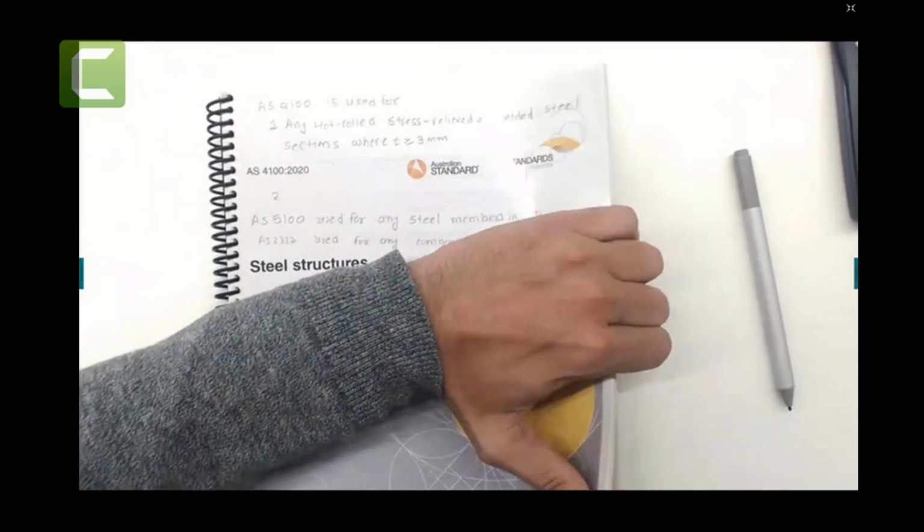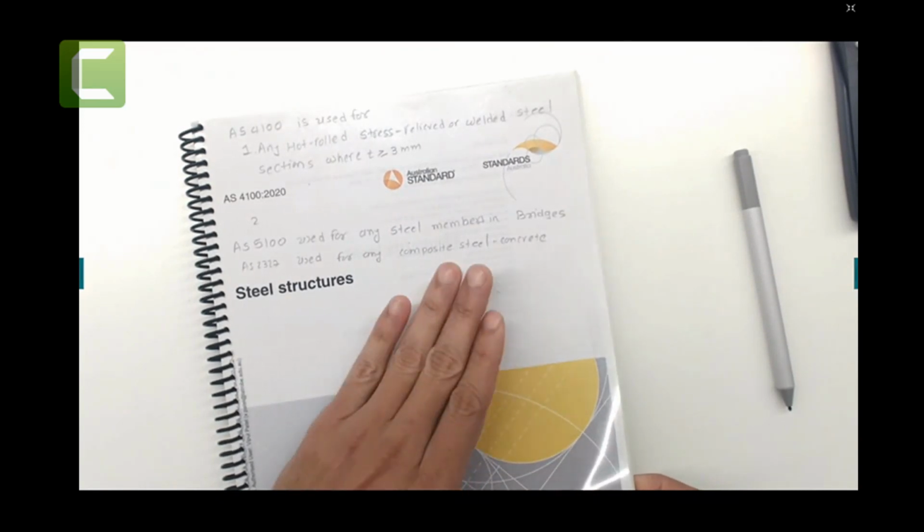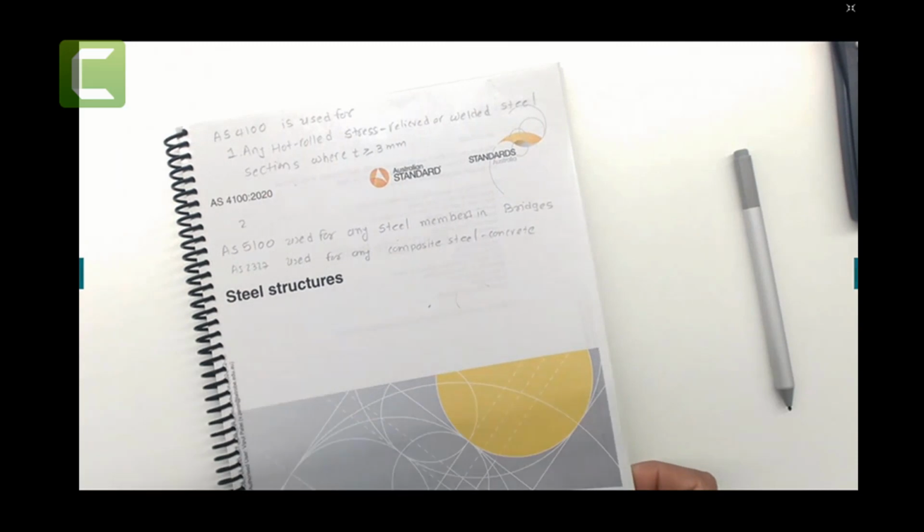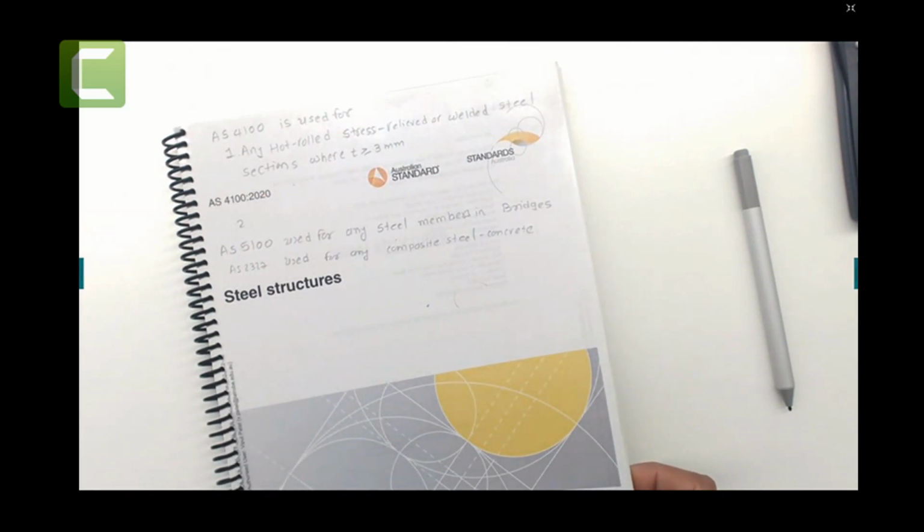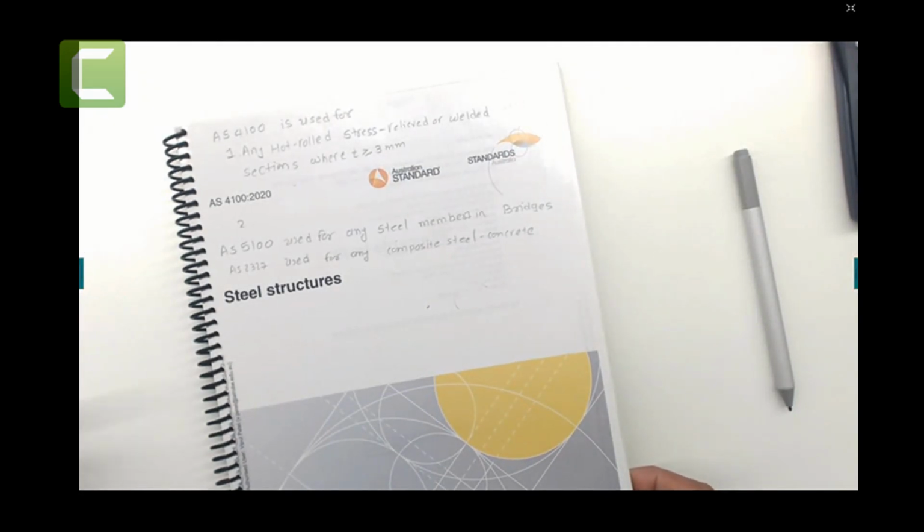But if I take this thick plate, I can't do it by hand, but I can heat it up and then easily I can do it and it will go. So this is the cold form process and hot roll process. The heavy sections, like the thick and strong sections, need the hot roll process. I hope you understand that. This is the simplest way I can explain it, or not really.